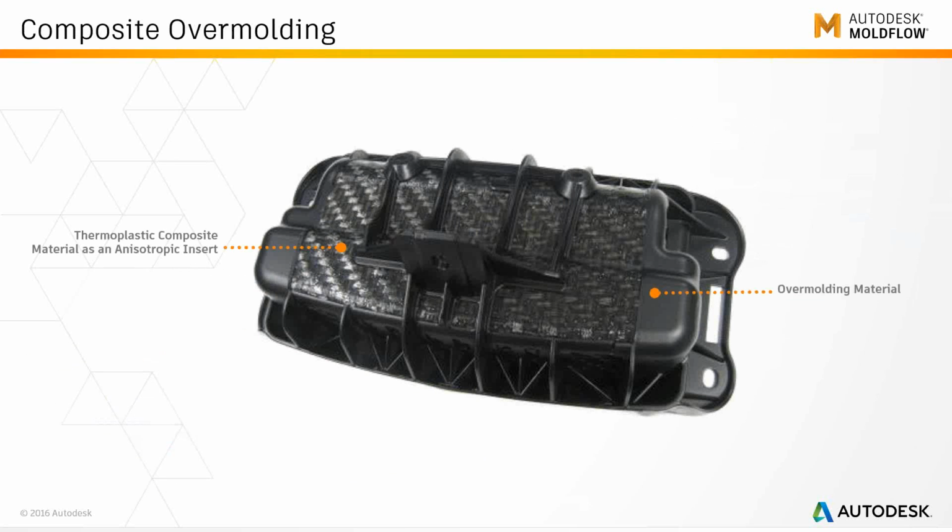For some customers that are interested in doing hybrid overmolding, let's say overmolding a composite structure, a thermoplastic composite structure, we now allow people to specify anisotropic insert properties. In the last 2 releases, I believe, we added the ability to specify orthotropic material properties.